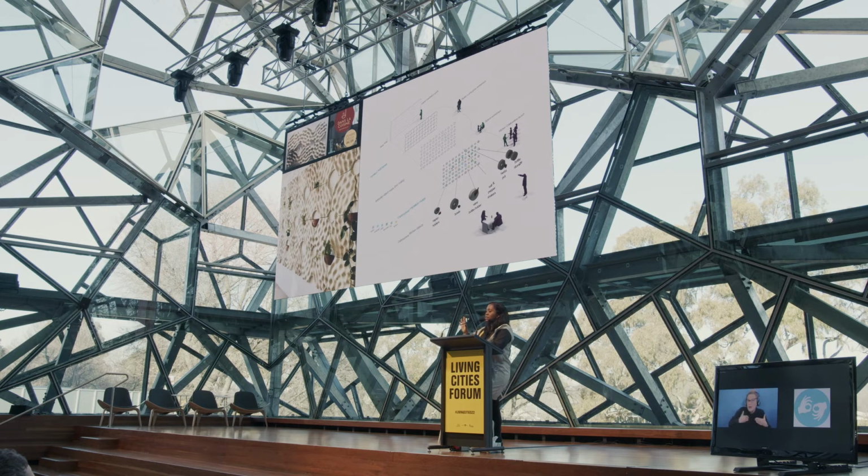And so you can see the base of the wall is made out of mycocomposites that use hemp, and that's been a material that has been very well characterized in terms of mechanical, fire, and moisture performance. And the more experimental, everyday waste that is coming out of the kitchen, which forms those insets, everything from lemon peel, citric-based food waste, to onion peels, to garlic peels, can be fed to develop experimental mycocomposites.